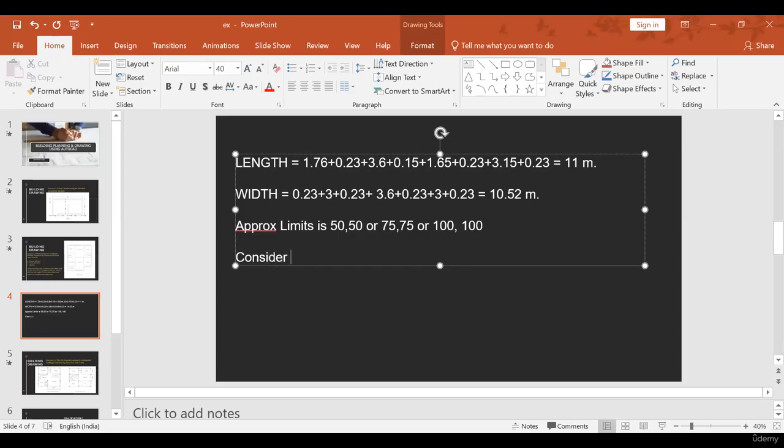So I will tell you, in the schedule of openings, what window size we need to take, what is the kitchen window, what is the living room window, what is the bedroom window, what are the bedroom doors, bathroom doors, storeroom doors, puja room doors, main doors. All the dimensions we mention in the schedule of openings when we're doing that.